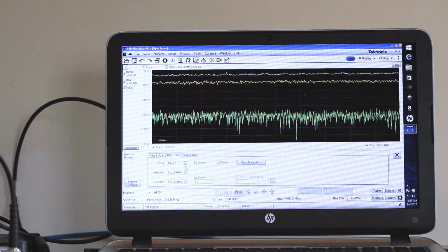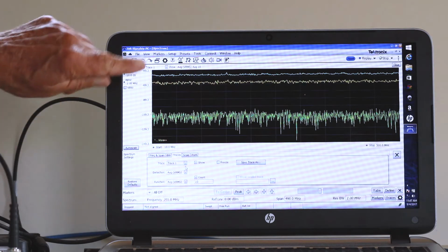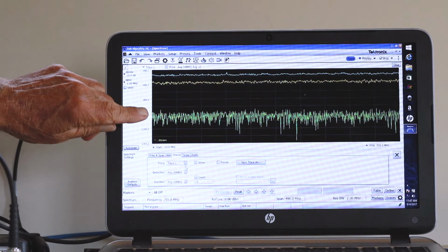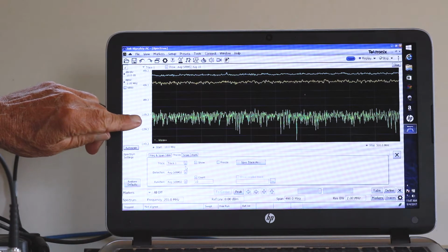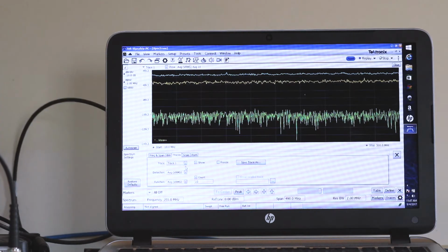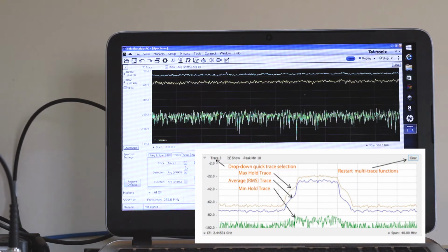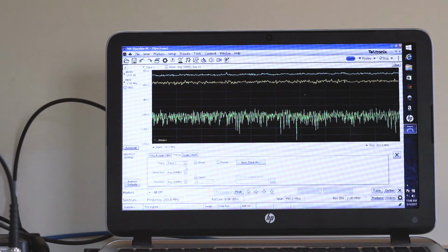The results show the 3 different traces displayed in the screen simultaneously. To acquire all 3, you may have to press Auto Test. The average trace is generated by multiple traces averaged together. There is one vertical value to each underlying frequency data point. Once the specified number of traces have been acquired and averaged to generate the displayed trace, each new trace takes the place of the oldest trace in the calculation.